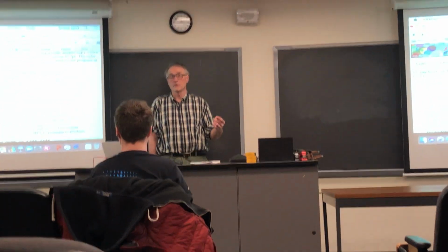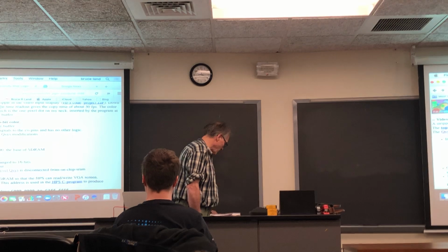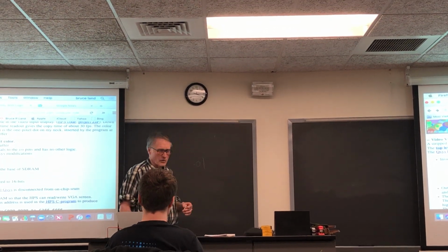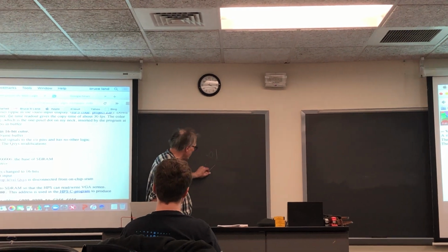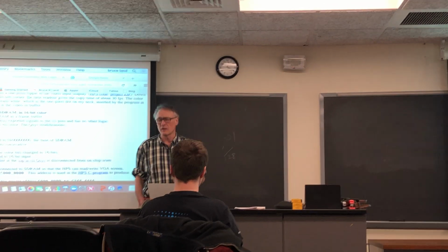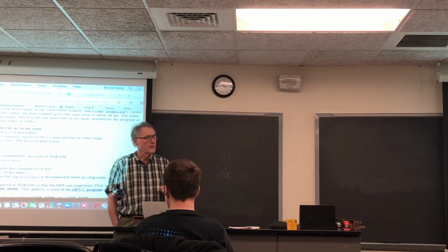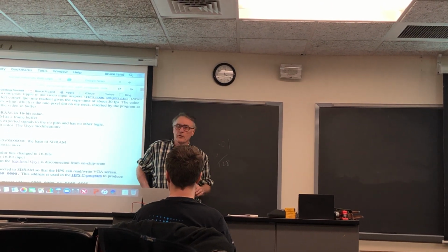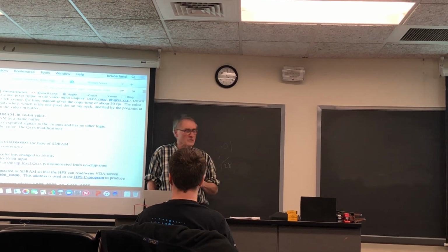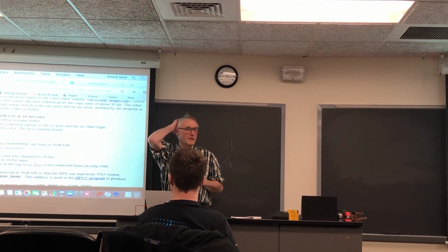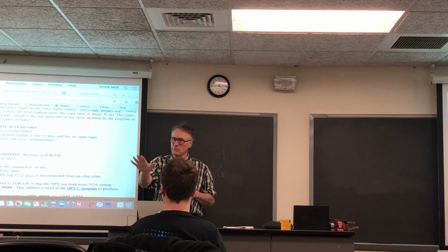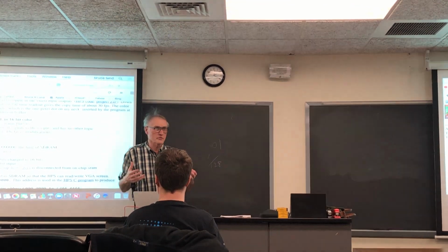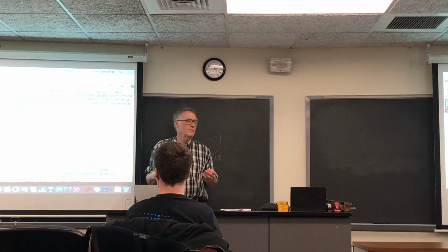And if you change dt, instead of 0.01, which doesn't match well with binary, to 1/128, both in the simulation and MATLAB, that's about as close as you can get, and it will still diverge after a few hundred cycles. That's why, to verify this, I'm asking you to also do the 3D plot in MATLAB, because the double scroll structure is relatively robust.